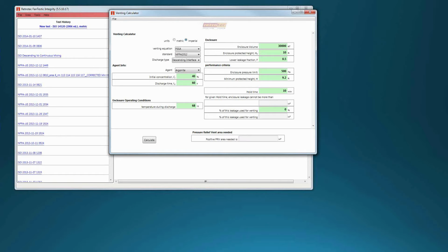What I was able to do with my door fan, just to convince myself that these enclosures would hold 500 pascals, is I took one of our new high-power fans, I cranked it up to 500 pascals and gave the wall a thump and said, seems to be holding it just fine. So I've actually experimented with this, and a wall that is poorly built might start to crack at 500 pascals.